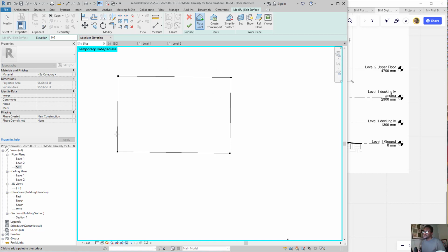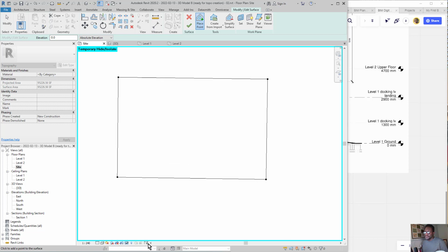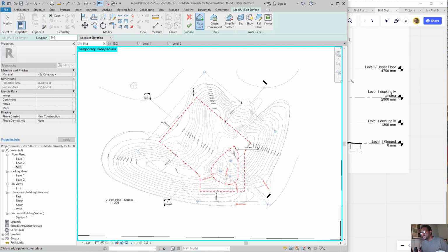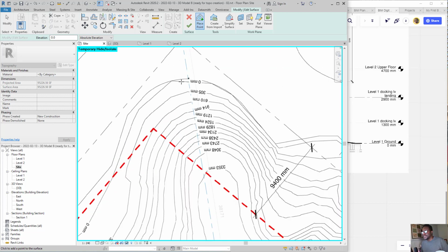Now once you draw this first contour line that's showing the boundary, notice that pretty much you have drawn a slab that is covering your drawing, right? That's no worries, we can simply switch to wireframe mode so that we can see our drawing again. There we go. All right, now the next thing that we're going to do is start tracing from the lowest point and going forward.